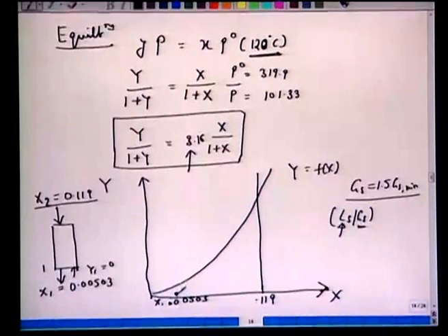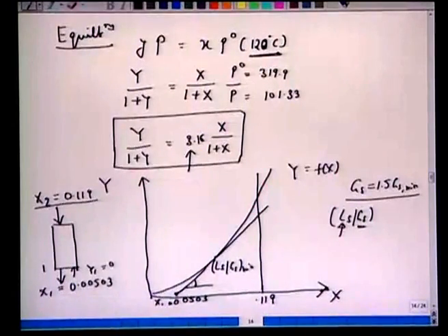Now we know 0.119 here, and to obtain this minimum, if you recall, we have to take a tangent because we can see a pinch here. So we have a pinch here which will give us 0 driving force, and we can get LS by GS corresponding to the minimum GS flow rate.